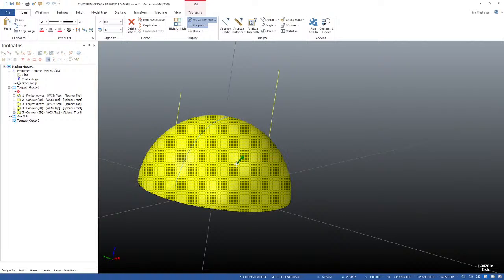And I can drag this arrow along my surface and get surface information. So it tells me, based on my current tool plane, what my current angle from vertical is. So vertical would be 90, flat would be 0, horizontal, what the radius of curvature of the surface is, and the diameter, and the actual point that lies on the surface.